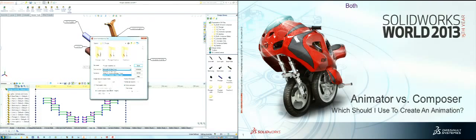Some other control we have, we can actually control the aspect ratio, so it's in here. The frames per second. One thing that you have to be very careful of in Animator is there are two places that frame rate is controlled. All the time we were creating animations down here, there's a setting in the motion properties that we can set a frame rate, and that's telling the solver how often it's got to solve. When we take it out here to record it, this frame rate could be different.